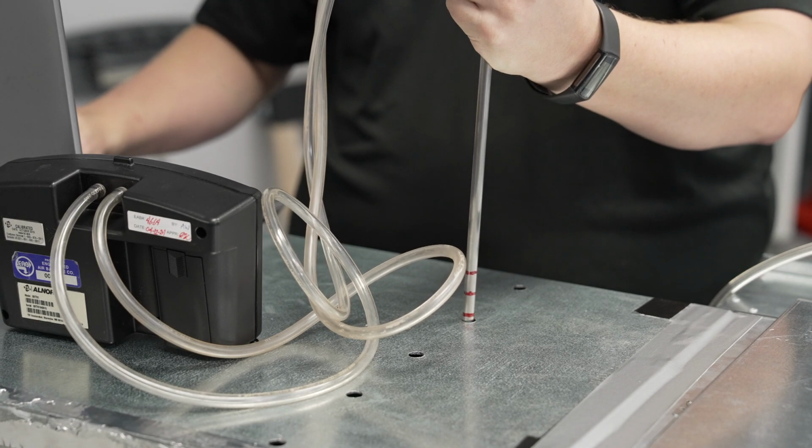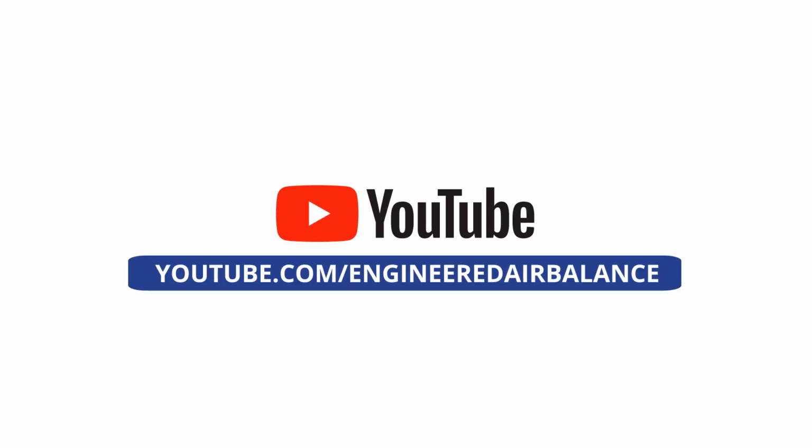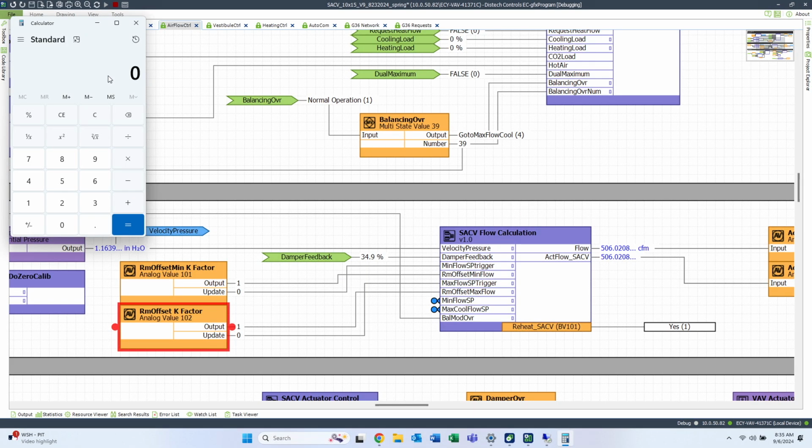For more information on conducting duct traverses, check out our YouTube channel at youtube.com/engineered air balance. In this case, our traversed airflow was 450 CFM, which we will use for all future corrections. Once we have our traverse, it's time to set up our correction factor. And for this one, we'll be using the control software.